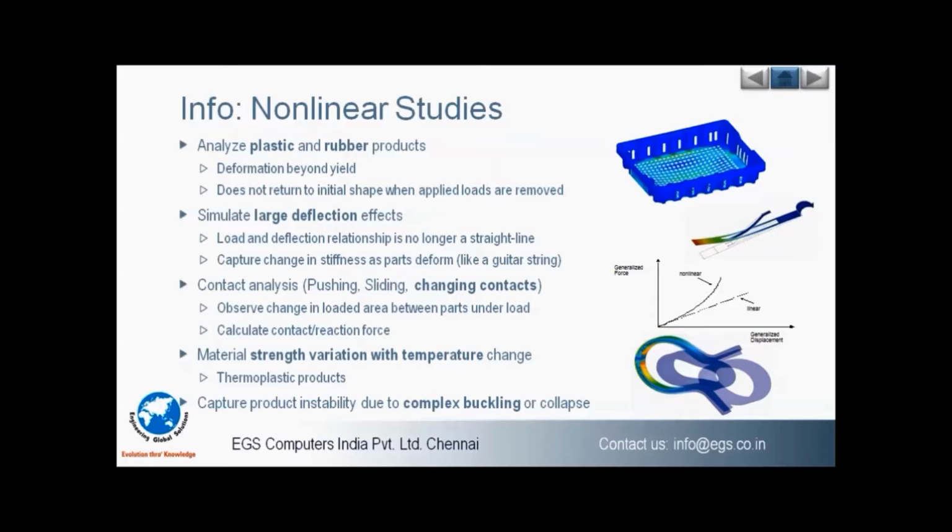So this study you can do with the nonlinear analysis, and we can study the loads and the deflections using a straight line, say when our product is no longer going to exhibit linear behavior. And we have the contact nonlinearities also when we are dealing with the pushing or sliding movement on the contacts. We are going to observe the change in the loaded condition for the parts when the load is applied. So we can also calculate the contact reaction or the reaction forces.